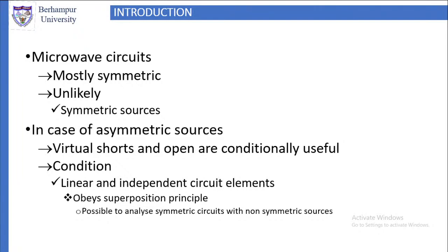Then, if they are linear and independent, that leads to a very good condition, that is the superposition principle. Linear and independent components always obey the superposition principle. If the superposition principle is obeyed, then it is possible to analyze the symmetric circuit with non-symmetric sources.